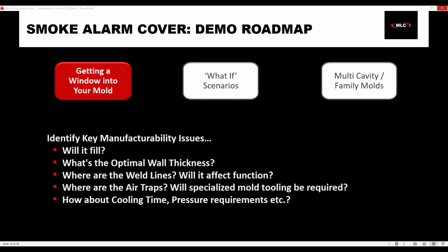Now this next section is the injection location. The injection location we have specified is over here. There are a couple of tools that you can utilize to help you decide what the best injection location would be. But like anything else, because we are running a simulation, you still may have to iterate through those to see and optimize what the best place would be. And that's something we'll see a little bit later.